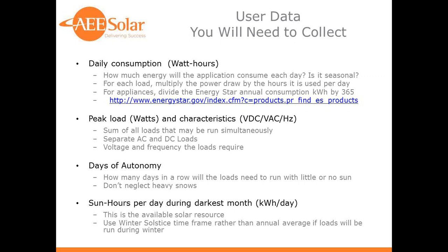So there's a bunch of data you need to collect when you're figuring out a design for an off-grid system. We need, obviously, to know what the average daily consumption is to get an idea of how large the system is going to need to be and what it needs to supply. The whole point of these systems is to run loads.